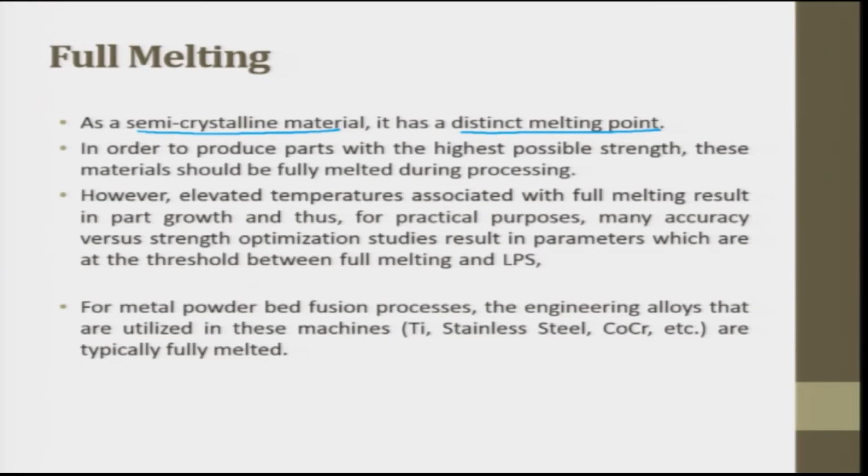However, the elevated temperature associated with full melting results in part growth, and thus for practical purposes many accuracy versus strength optimization studies result in parameters which are at the threshold between full melting and LPS. So, this portion is very important.